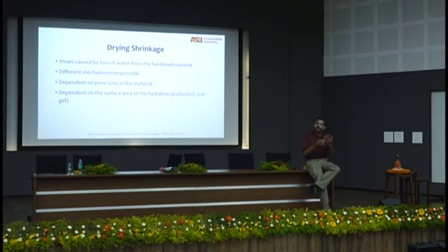So, when you teach class also, don't ask a question in your exam saying that assume that you are pushing a body with a force of 100 newtons. You cannot push a body with a force of 100 newtons. The 100 newtons is actually imposing a displacement on the body. The body is sitting and saying, oh, somebody is compressing me by 3 millimeters. It does not know what 100 newton is, right?